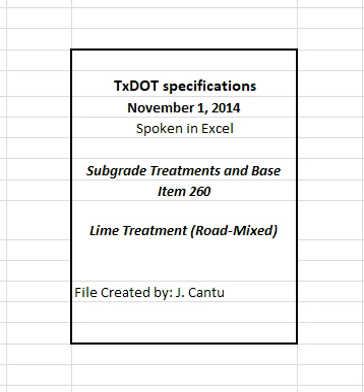Suspend application when the engineer determines that weather conditions are unsuitable. Minimize dust and scattering of lime by wind. Do not apply lime when wind conditions, in the opinion of the engineer, cause blowing lime to become dangerous to traffic or objectionable to adjacent property owners. When pebble-grade quicklime is placed dry, mix the material and lime thoroughly at the time of lime application. Use of quicklime can be dangerous. Inform users of the recommended precautions for handling and storage.